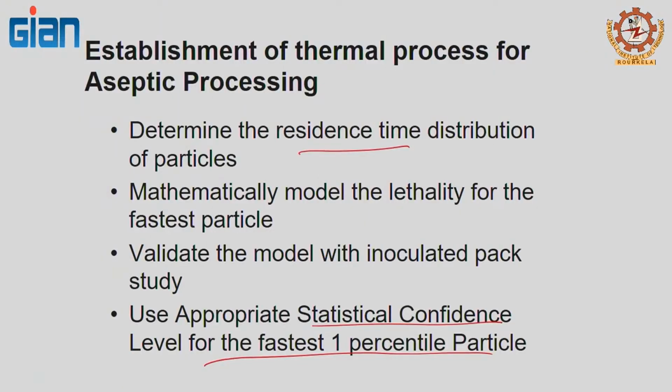Why the significance of moving fastest in the holding tube? Because when a particle is moving fastest in the holding tube, it is spending the least amount of time in my whole tube. Remember, the holding tube is the place where I am demonstrating the safety. So, that means if I spend less time in the holding tube, you may have a microbe in that particle that can contaminate the entire batch. So, you want to make sure that that particle is inactivated and free from pathogens and so forth. So, that is where they are able to look at the fastest moving particle with certain characteristics.